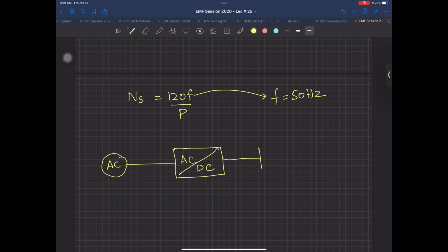From that rectifier, I again convert it into AC, but giving from a microcontroller a frequency signal of approximately 25 Hertz, supposedly. With a microcontroller, by just one button or maybe one potentiometer, I can change this frequency.